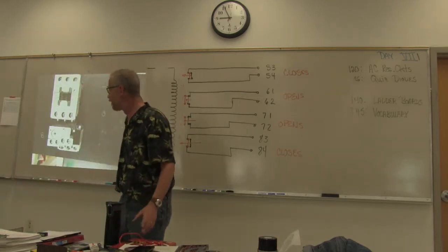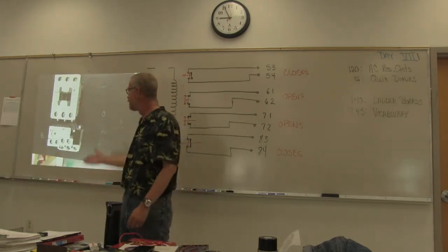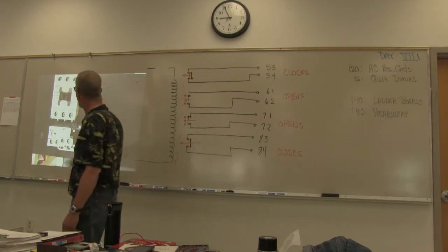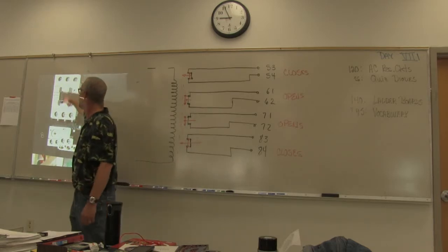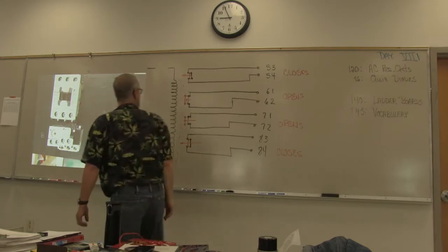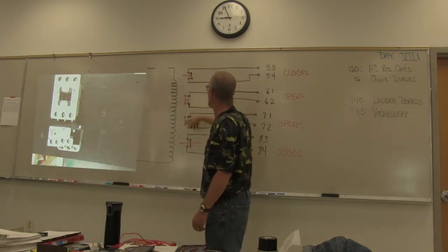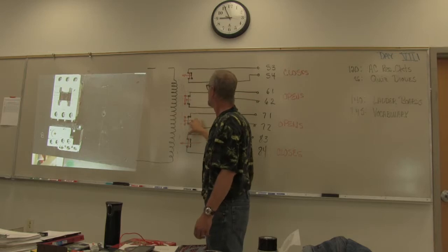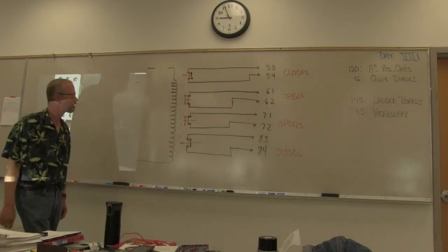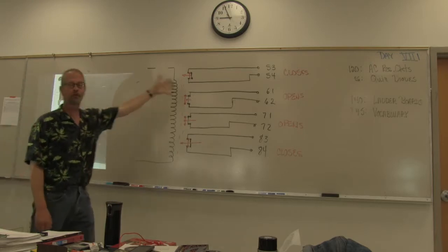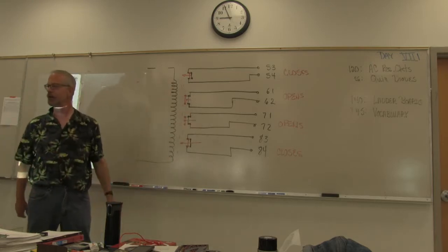And the nice thing about it over here is that you're only working with a single phase. This is the 3-phase compatible. You don't have to use all of them, but if you thought about this as having 3 normally opens, then you could use them as a 3-phase connection. One phase to control 3. And that's what you see on your motor controller.